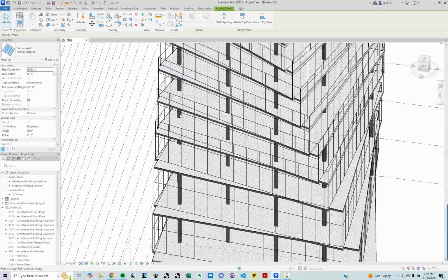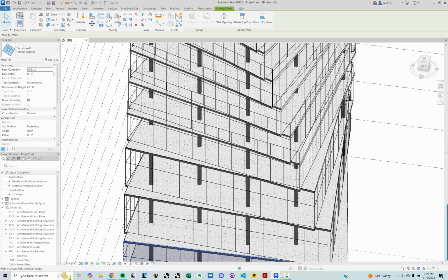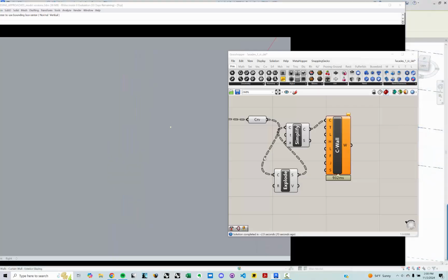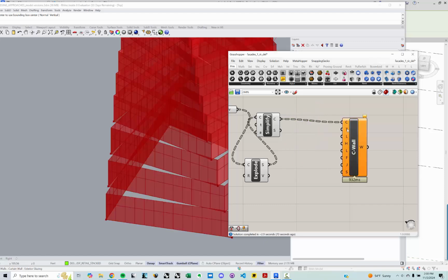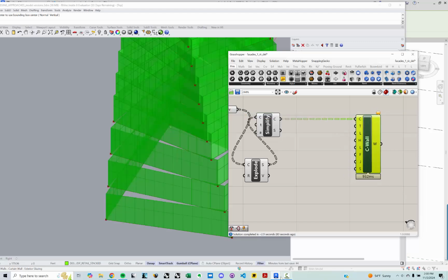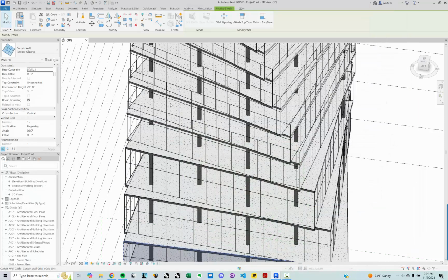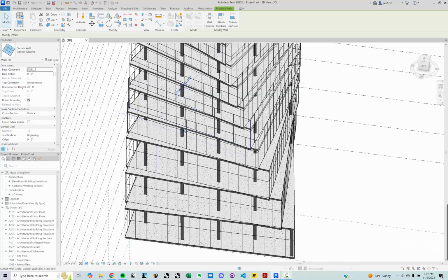So here it's okay. Up here you see it's flying past. We don't want it to do that. We want it to connect to the floor above. So there's a few ways we can do that. I'm going to come in here. This is going to ask me for the type, the level, and the height, right? So first, what I want to do is the level should be getting assigned automatically. Let me come back into here and check. Level 5, and then there's no base offset.